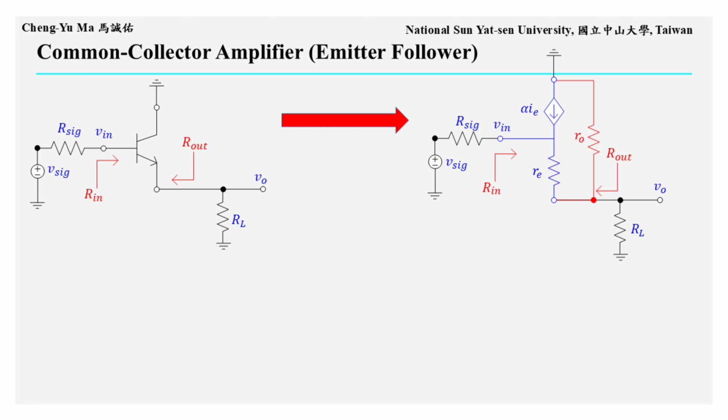In this case, including the early effect output resistance RO does not make the analysis much harder. In the previous CE amplifier with RE and CB amplifier analyses, we ignored RO because including it would make the circuit analysis much more complicated for beginners. A complete treatment of RO will be left for Electronics 2. In Electronics 1, we include RO only when the circuit remains simple.